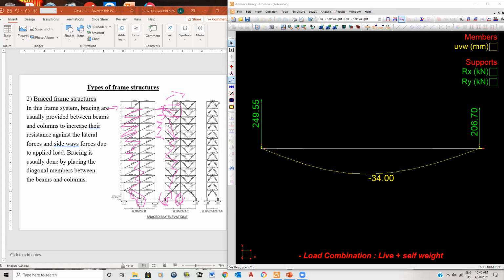So if I didn't have a frame in here, when I would have a lateral load, and if this wasn't a rigid frame, well, as soon as the load would go on it, the whole thing would just collapse on you. So these are brace frames, and this is very, very typical for structural steel, okay, because it's easier to put in a brace than to actually do a frame with structural steel. It's less expensive. And for concrete, you do a rigid frame because it's much easier to make a rigid frame than to make a brace frame in concrete.